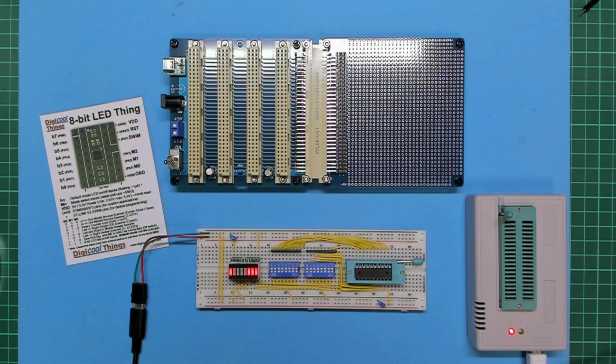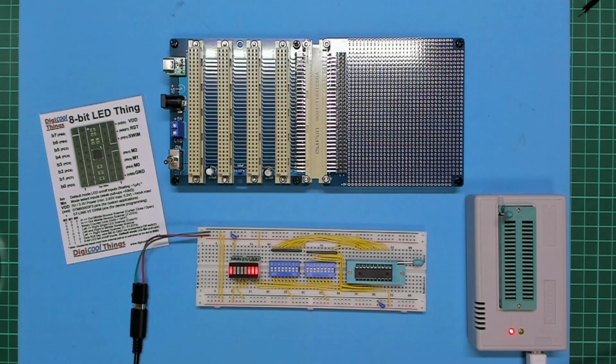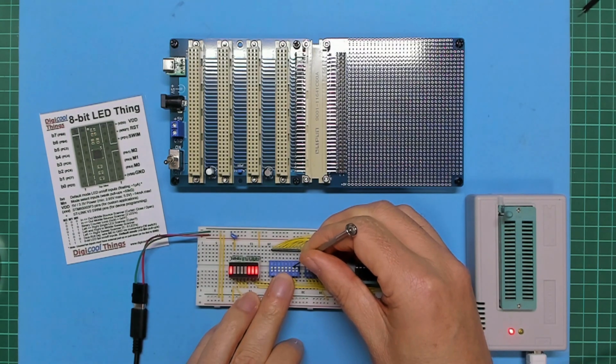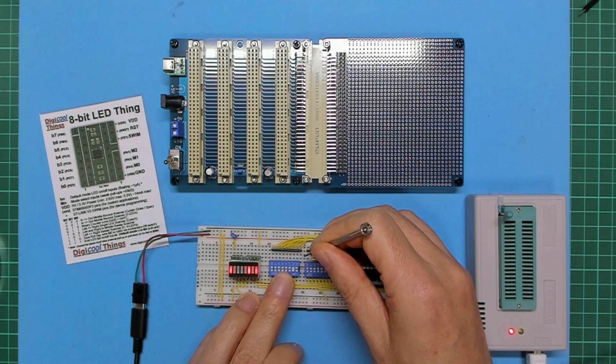So if the logic has programmed correctly, switching each of the pins 1 through 3 to on, so they are pulled low, we should see each LED go out, as the 3 outputs correctly follow the pins 1 to 3 inputs. So let's try that out. I'm going to switch pin 2 first, which should take the middle LED off. Yes.